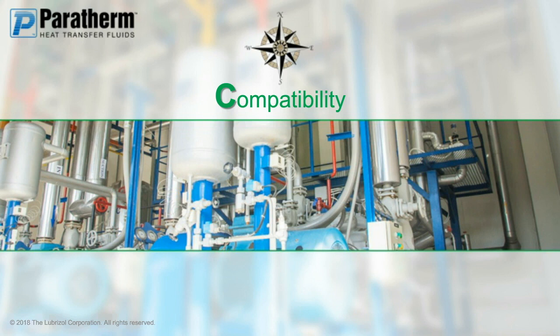So one of the key conditions of your inherent system is, I have a system here, it's got certain polymers, it's got gaskets, it's made from certain kinds of metals. I need to make sure that I'm choosing a fluid that's going to be fully compatible with all of my equipment. That comes in the form of pump seals, that comes in the form of the heat exchangers that you have, everything along the way, you want to make sure that you're looking at materials of construction that are going to be compatible with the fluid that you choose.